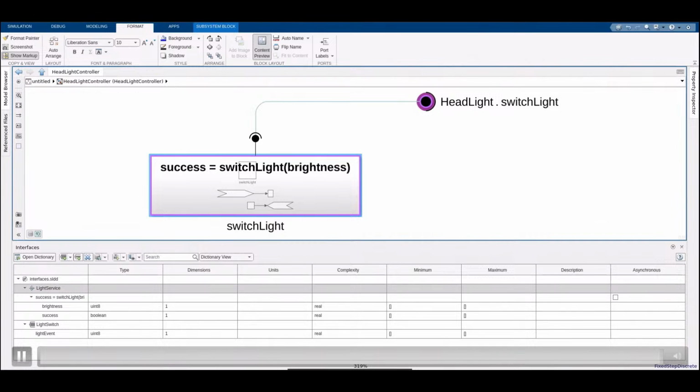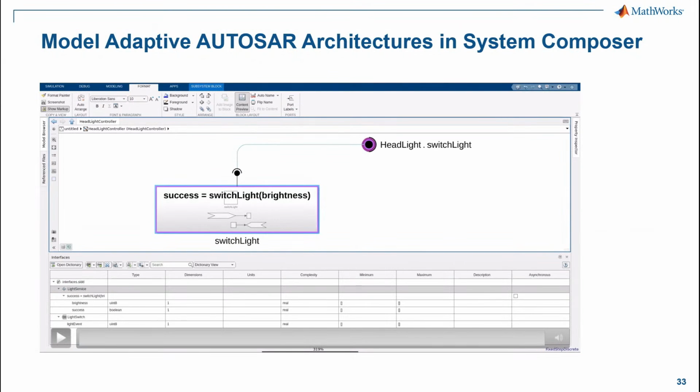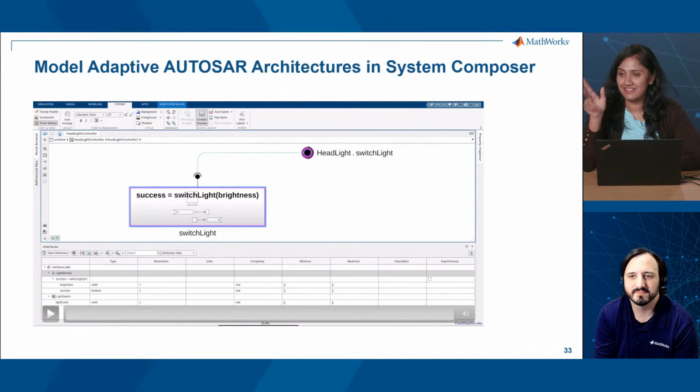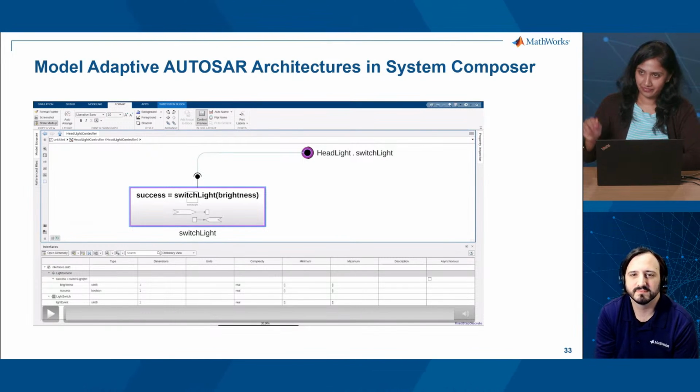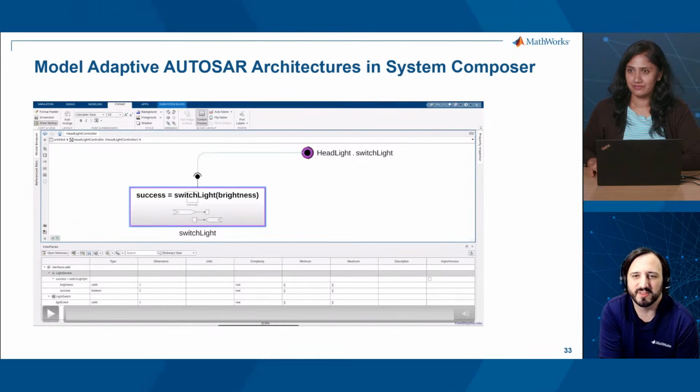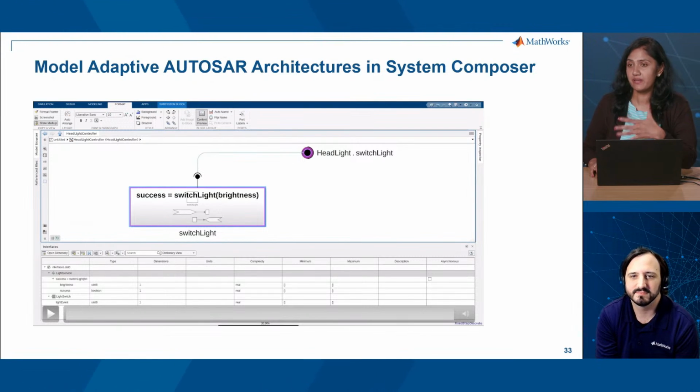It didn't have that initially when I created it, so it will look for the Simulink function. That's the beauty of using this client server port, and that will use the function port and the port scoped Simulink function with that. So then I'm not just stuck with rate-based models. Exactly, right. Nice. MATLAB is investing a lot in supporting this service-oriented architecture. So AUTOSAR Adaptive is based on the service-oriented methodology.